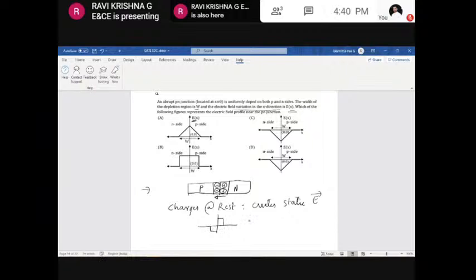So if you calculate the electric field based on the potential gradient, we will get something like a ramp function, because we need to integrate this particular distribution. So among these, we will get this to be wrong, because here the electric field is negative on the N side, but on the N side we should have positive, right? We should have the positive electric field on the N side. Later on, on the P side, it should decrease. The electric field is going to be pointed in this direction, which means on the N side the electric field should be positive always for this particular case.